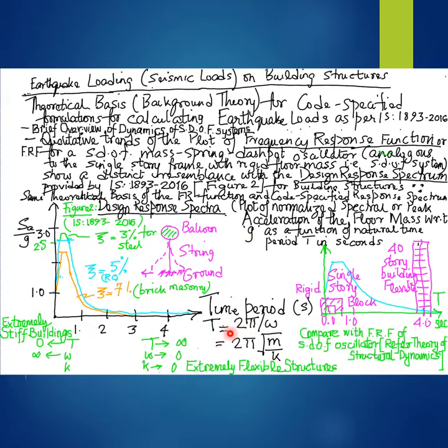And in case of such extremely flexible structures with extremely long time periods, for example, this 40-story building frame depicted in this figure on the right extreme of the design response spectrum, estimated to have a natural period or fundamental time period T of approximately 4 seconds,